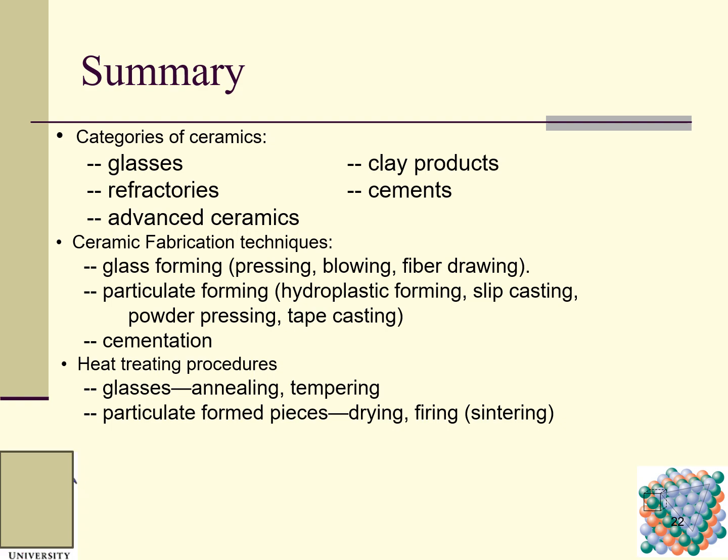And summary, categories of ceramics. We have glasses, clay products, refractories, cements, and advanced ceramics. And ceramic fabrication techniques: we talked about glass forming, for example, pressing, blowing, and fiber drawing; particulate forming, hydroplastic forming, slip casting, powder pressing, tape casting; and cementation.